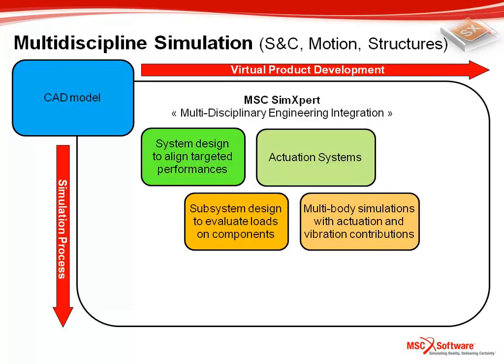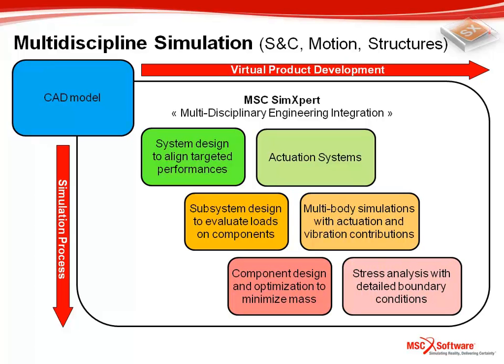The subsystem design to evaluate loads on components is achieved through multi-body simulations with actuation and vibration contributions in the motion workspace, and of course component design and optimization to minimize the mass. This is possible in the structures workspace with stress analysis along with detailed boundary conditions.